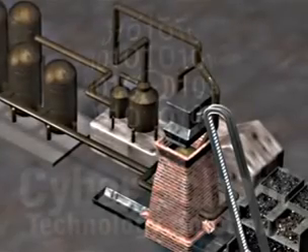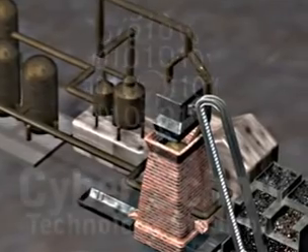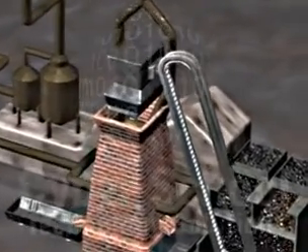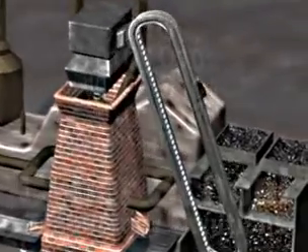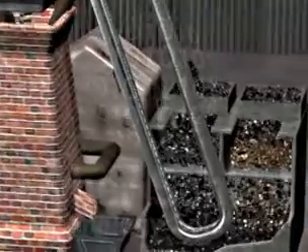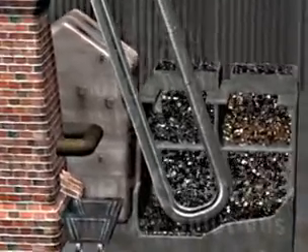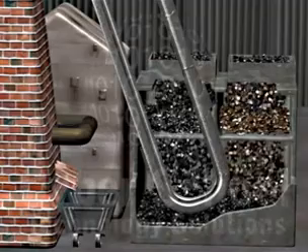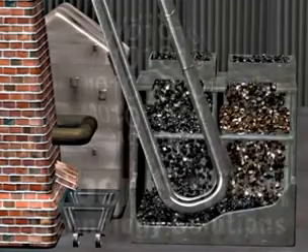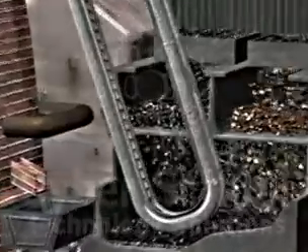In the blast furnace, iron is extracted from iron ore, hematite. In the preheating furnace, iron ore is mixed with coke and limestone and carried to the charging tower by the conveyor belt. Now let us look at the cross-section of the blast furnace. The cone or sealing valve arrangement is lowered to allow charge into the furnace. When closed, it prevents waste gases from escaping.